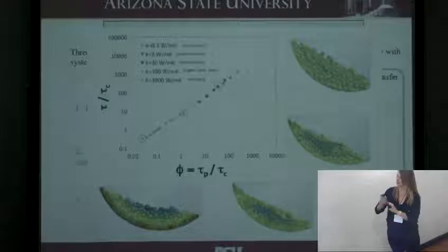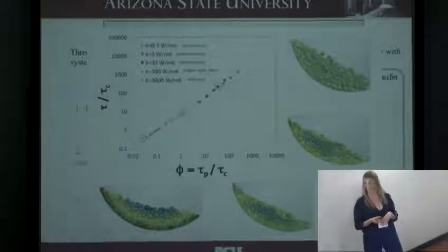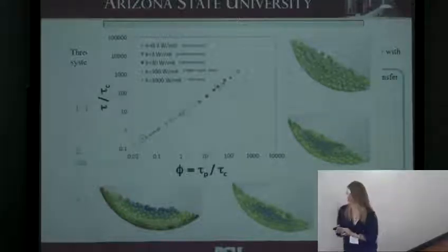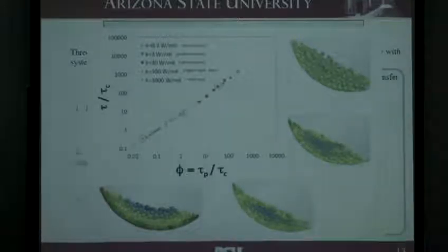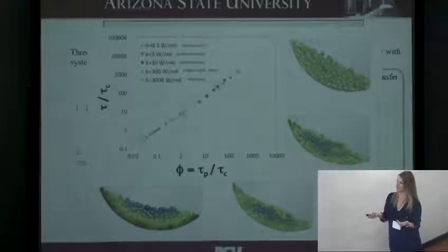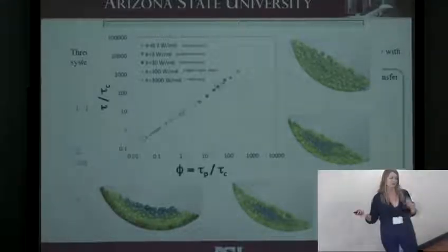A couple things to note here. This is a really cool result, but it's only valid for this certain fill level. We did a 13% fill level, and for this particle size distribution: a mean diameter of 4 millimeters with a normal size distribution. This was all just DEM simulations. So from here, first I wanted to really validate this with experiments, because we have no idea how accurately this represents experiments, and then to try some more conditions that we know will be important, like fill level, which is obviously going to have a huge effect, as well as particle size.